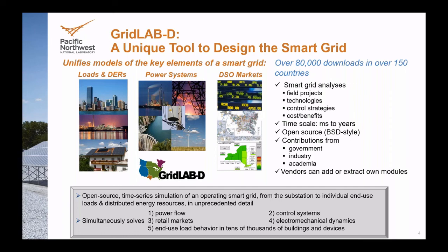Just some key highlights on GridLAB-D itself. As I mentioned, it is mostly for smart grid oriented projects. Basically a lot of your multi-domain work where you have things like a building model interacting with a distribution system electricity model, maybe interacting with some type of pricing scheme or retail market. And if you really want to go into it, if there's any communication infrastructure you want to overlay as well. And that's something I'll get into later in the presentation. GridLAB-D is very flexible in terms of the timescales you look at. It can do milliseconds up to years.